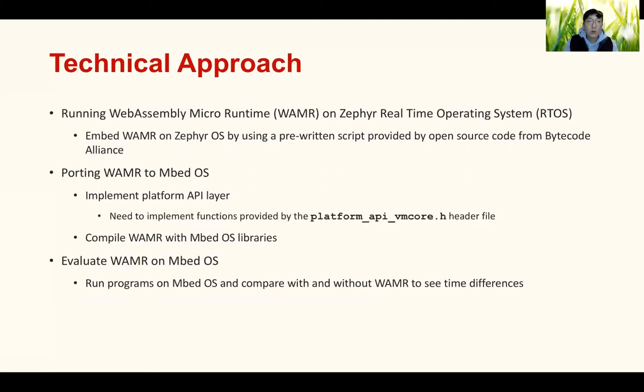And our technical approach for this project would be to first run Zephyr with WAMR. Next, we aim to port WAMR to Mbed OS. It's a little more complicated because WAMR is not supported on Mbed OS, and so we have to implement the platform API layer ourselves. After implementing the layer, we can compile WAMR.